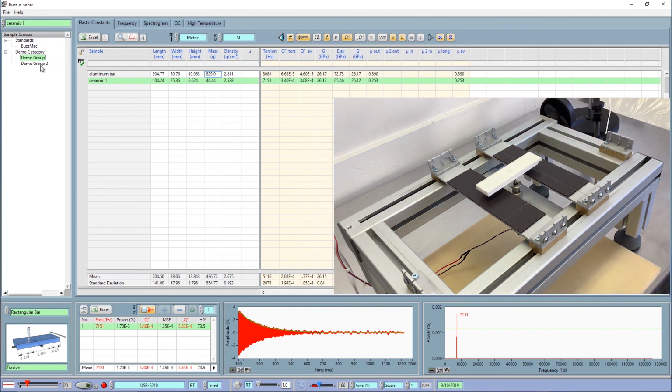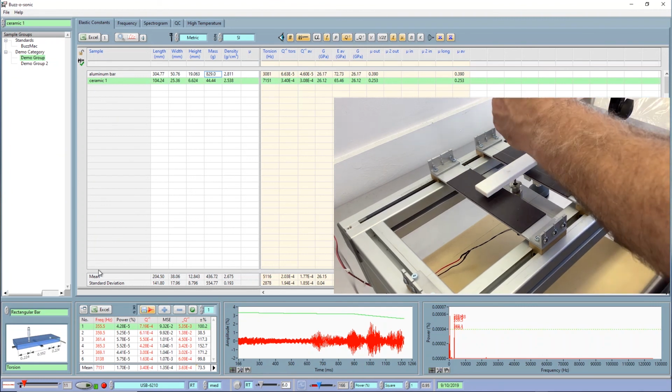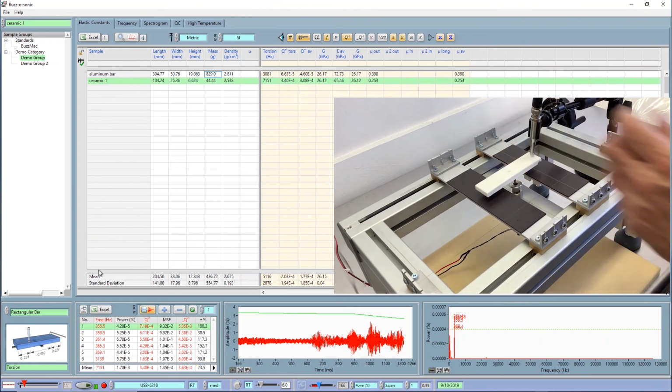Now we're going to use the automatic impulse tool. That's this one here. If you've got this attached, you will need to put some value here. This is the power that goes to the impulse tool. So let's try a value of, say, it's just volts times amps. Let's try 3.8. Not enough power, so let's just type it in. I'm going to type in 6. Now I can bring this down a little bit. So we see that would go past there. Now what we can do here, I didn't put the microphone over the sample. It's a good idea to put the microphone over the sample, that's probably why.